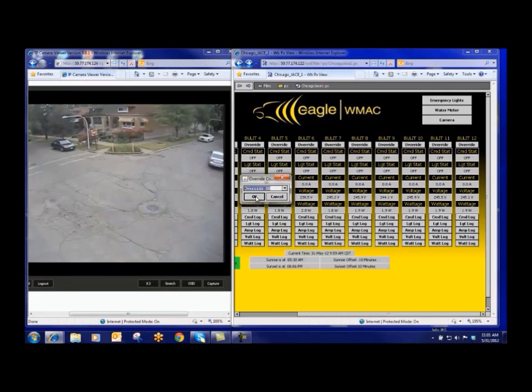So let's give it the command on and see what happens. Alright, we got the command status. Light status again will not change until we read current. We're starting to read current. It's currently 5.2 amps and an inrush of 1011.2 watts. Now if you watch the bulb, you'll start seeing the lights come on. The wattage will level off again as the bulb fires up and then cools off.